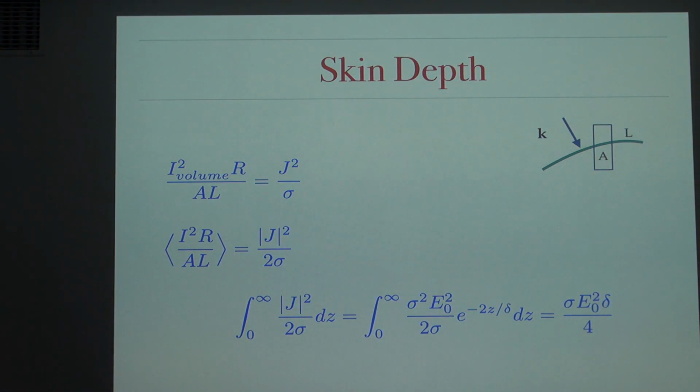So now this simple calculation, I mean a very simple property of a Maxwell equation, explains why there is a better way of sending electric signals via a bunch of thin wires than via one very thick wire. Because if I have one very thick wire, the skin depth, the thickness over which the electric current can propagate, is the same as for a very thin wire.